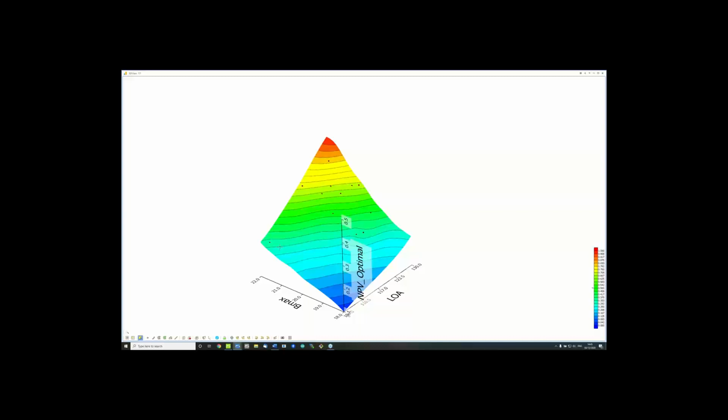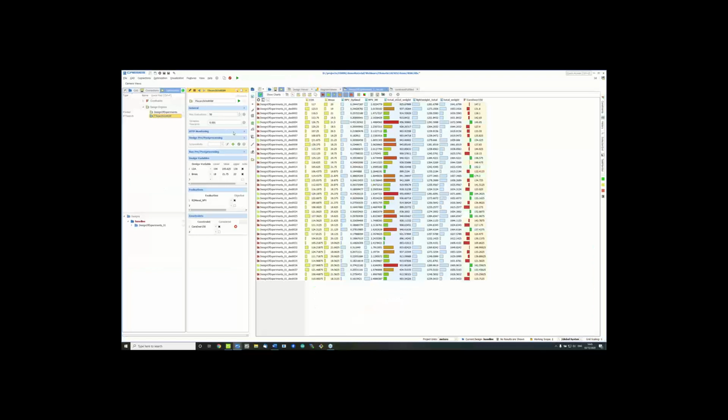I will use this data, as I've done already, to set up a surrogate model, a response surface model. And as you can see here, I'm able to evaluate that model on any point within my design space. That means I can also run an optimization on that very model. So if I start by selecting this design on the bottom left, I can set up a T-search.